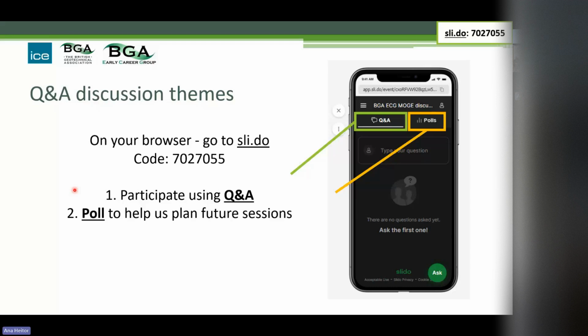I guess I'm not actually a great mathematician, but I think the physics of a problem is always more appealing to me. I think I say in the preface to my book, it's a physical approach. It's getting the physics right and trying to keep the maths as simple as possible. And for me, that's the thing with flow. A flow net is actually a solution to a differential equation, not a particularly complicated one, the Laplace equation. But what it forces you to do is think about the physicalities of the problem.